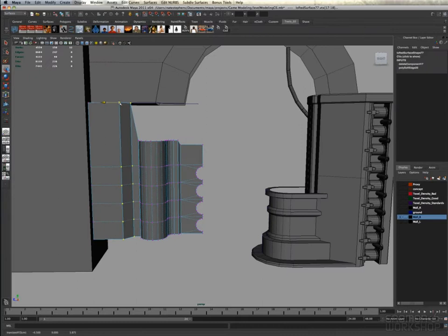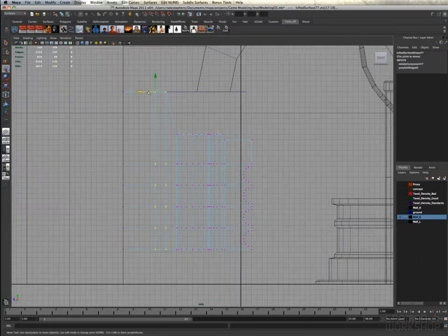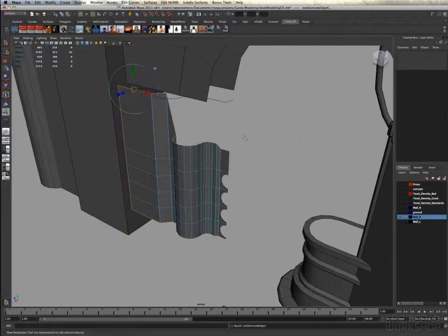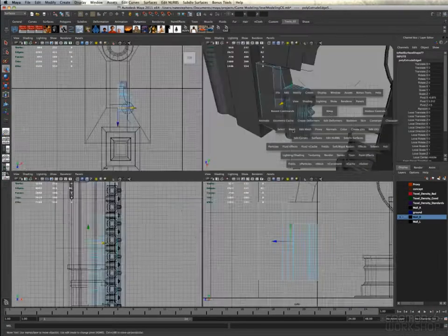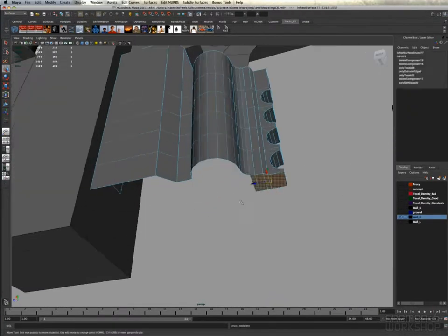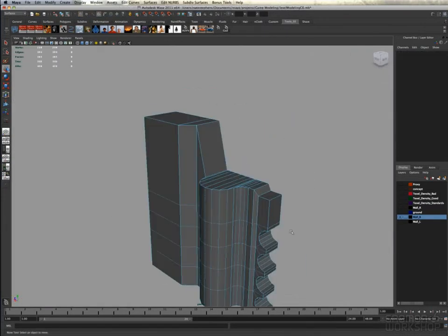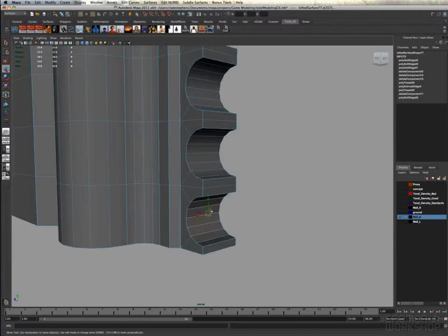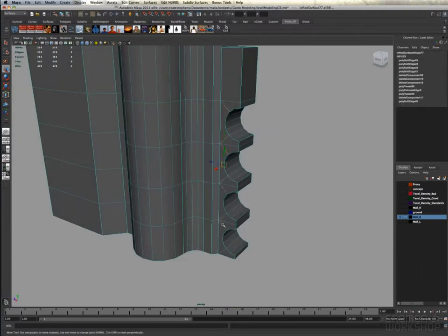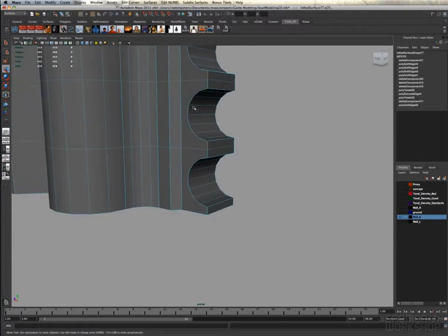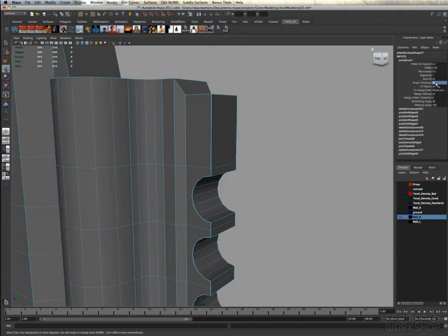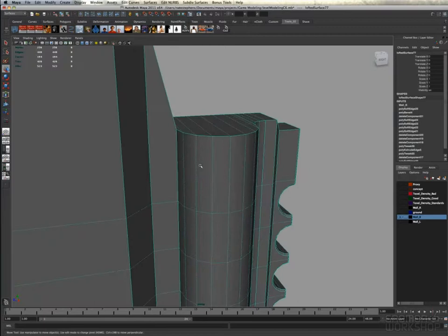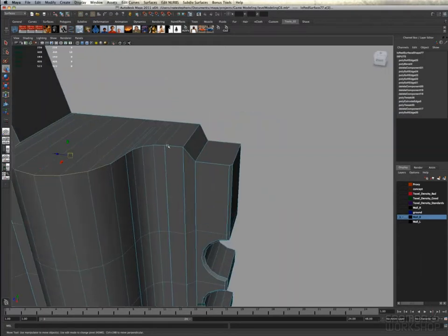It's important, if you use this technique of modeling curves and snapping them to primitives, if you're using anything that's circular or round, make sure that the amount of edges that it has is something along the lines of the power of 2. And what I mean is, if you make a cylinder, make sure that it has 8 sides or 16 sides or 32 sides, something like that, because that will correspond with texturing and also with your grid.